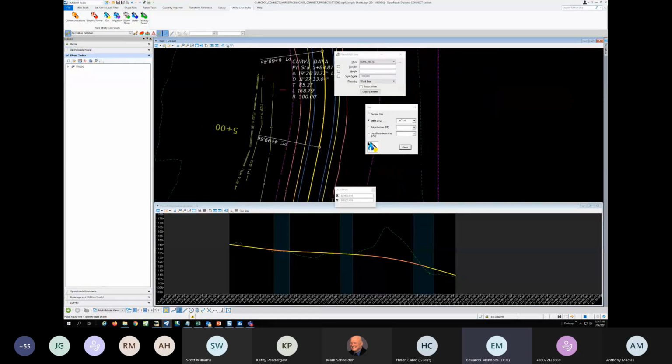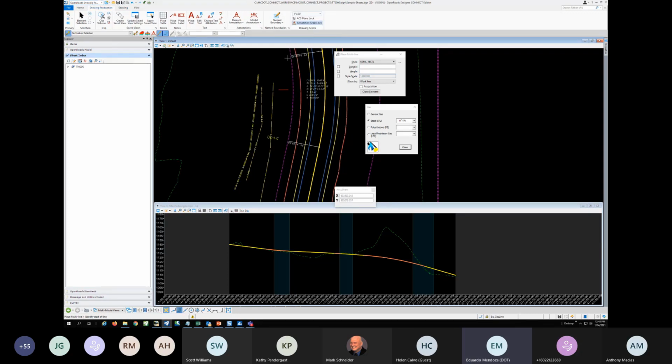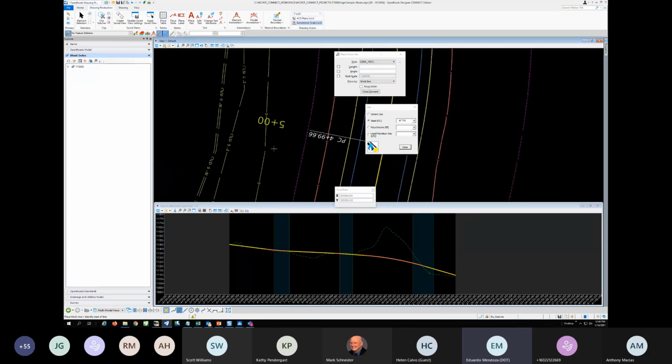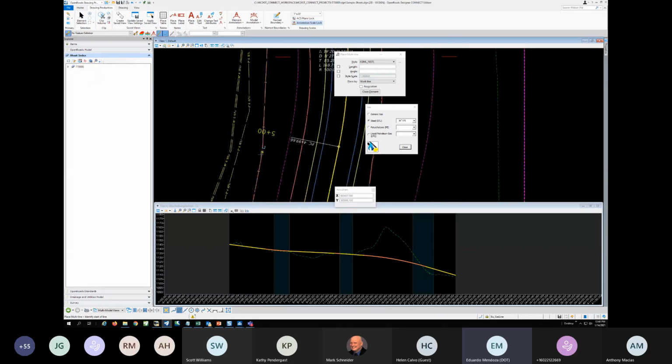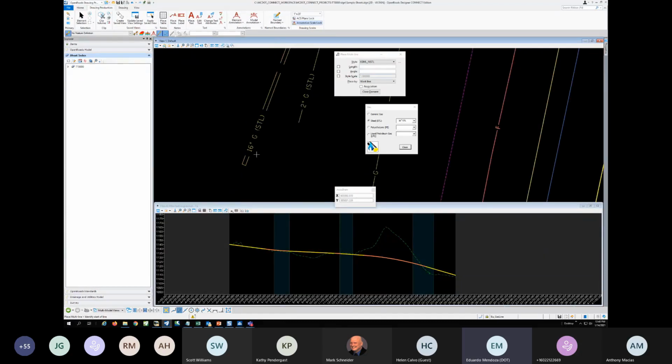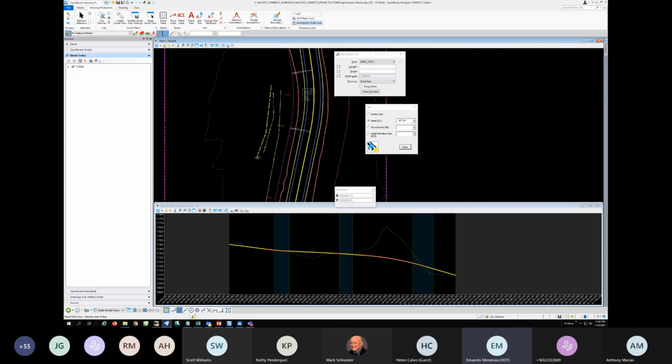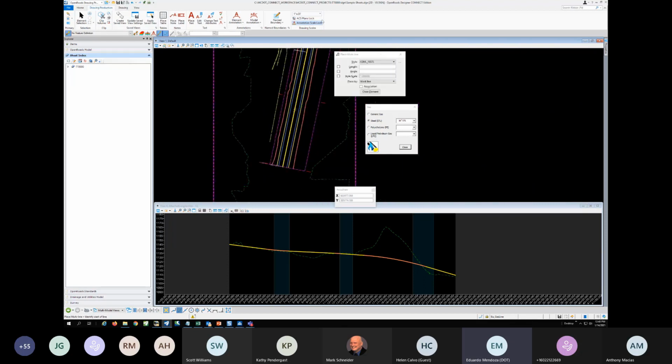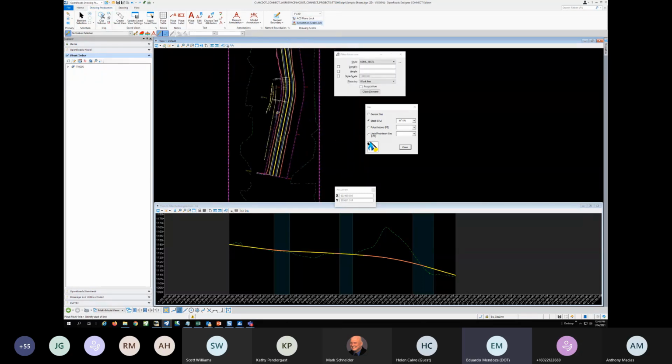And then the other thing is that if you were to go to the drawing production and change your scale, right now it's set to 1 inch equals 40 feet. If I change it to 1 inch equals 20 feet, everything changes, including the utility line styles. But for instance, the multi-line line style, if we were to measure from here to here, it's still 16 inches for the diameter, but the text does get larger or smaller depending on the scale that you're going to ultimately print to. I'm going to go to 1 inch equals 40 feet, and that's what I'm going to use for this.